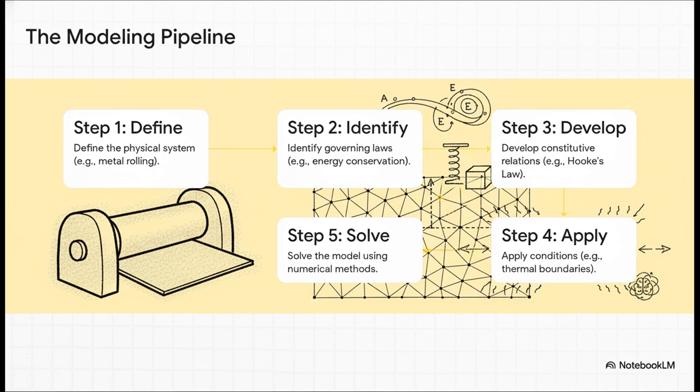Is it elastic? Is it plastic? Then, in step 4, you apply the specific conditions. The temperature, the boundaries, the forces you're putting on it. And finally, the moment of truth. Step 5, you solve the whole thing. And because of the mind-boggling complexity here, you're pretty much always going to need powerful numerical techniques to get an answer. We're talking about things like the finite element or finite volume methods. This is where the heavy-duty computer power really comes into play.